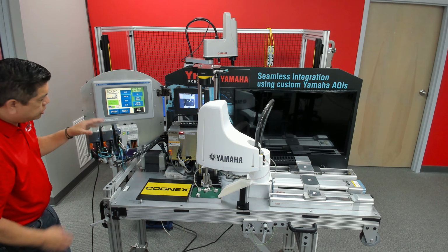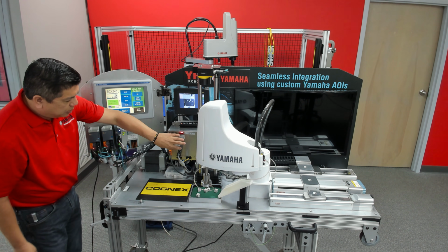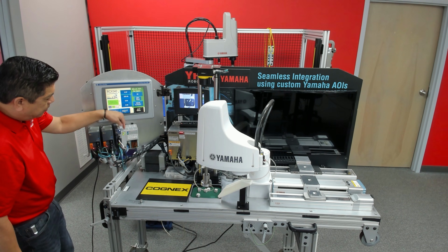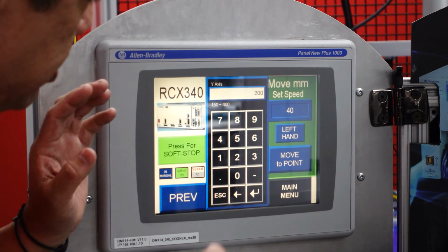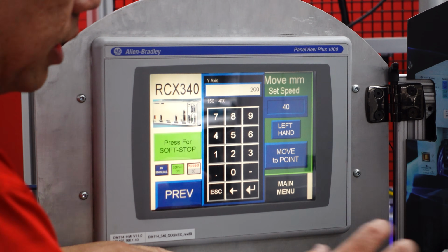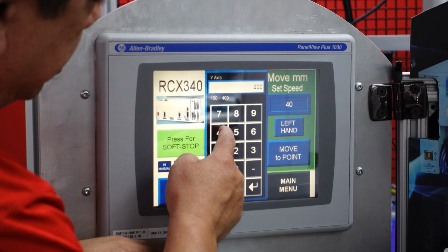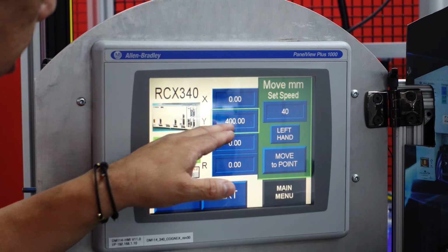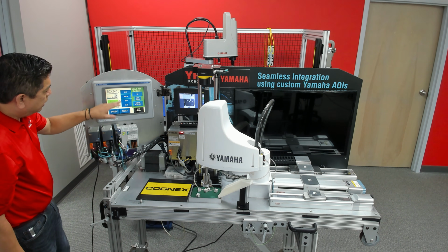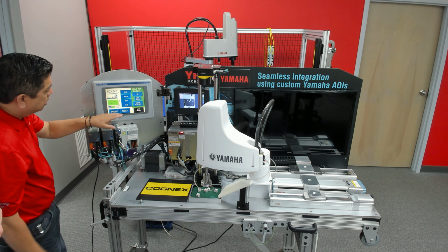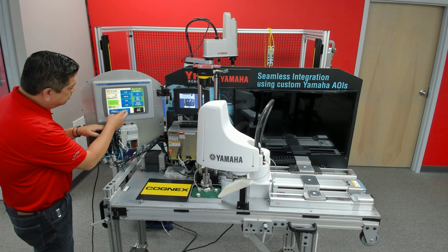Now, if we want to, we can actually store the positional data of the robot in the PLC, and that would be more desirable. Okay, so this is a move block, and since this is a 400 millimeter SCARA, we can actually type in the value of the tool center point directly into a move block. I'm telling you this to lay a foundation here.